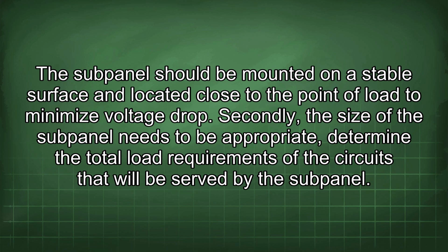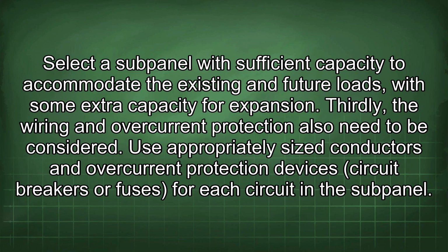Secondly, the size of the subpanel needs to be appropriate. Determine the total load requirements of the circuits that will be served by the subpanel. Select a subpanel with sufficient capacity to accommodate the existing and future loads, with some extra capacity for expansion.